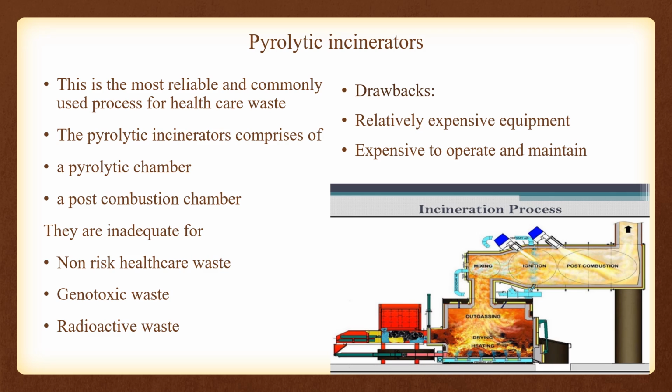The pyrolytic incinerator comprises a pyrolytic chamber and a post combustion chamber. In the pyrolytic chamber, the waste is thermally decomposed through an oxygen deficient, medium temperature combustion process of 800 to 900 degrees centigrade, producing solid ashes and gases. The pyrolytic chamber includes a fuel burner used to start the process, and the waste is loaded in suitable waste bags or containers.